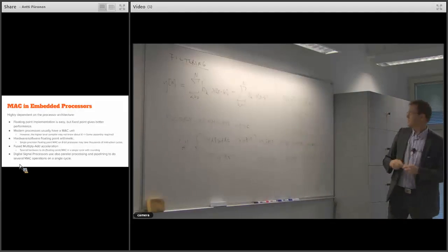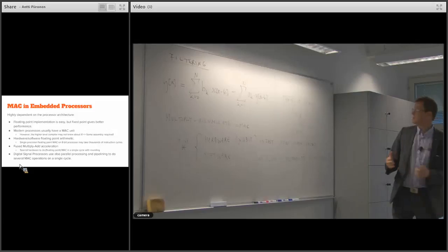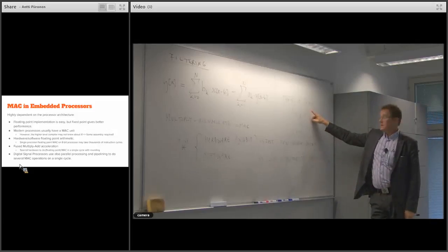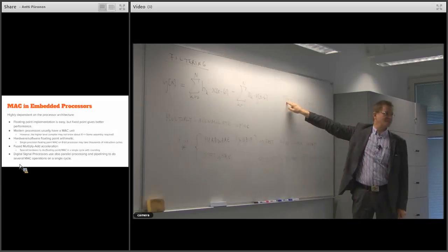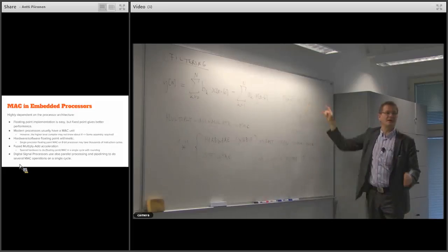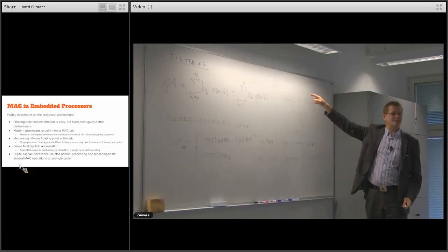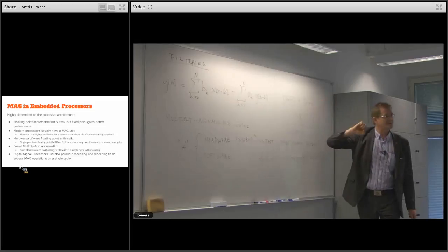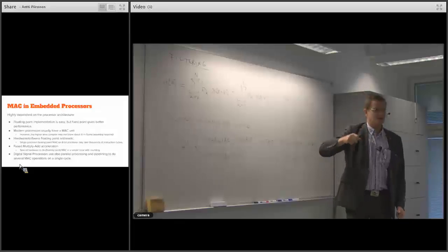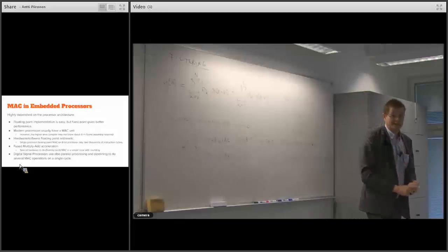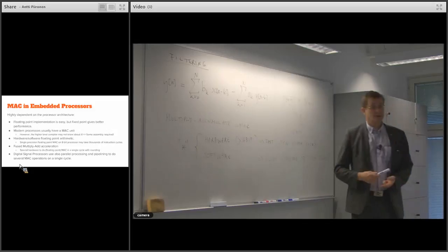Okay, so there is some room for the rounding. If you do the rounding at all, you could save some space by starting from 6 bits on one and 6 bits from another one, and still get about the correct kind of results, or get the data as 8 bits, but then the coefficients only 6 bits, sometimes even 4 bits. These kinds of things are quite usual in FPGA filter design, since you can make FPGAs do the digital filtering.